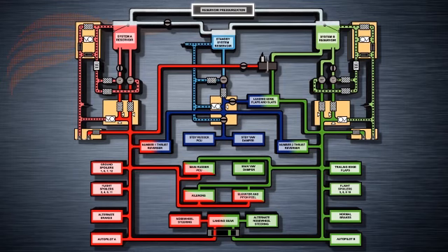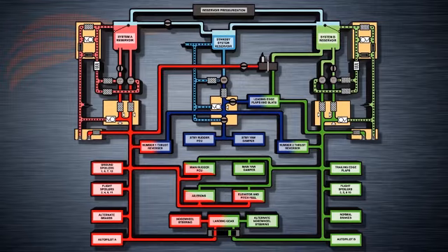If the bleed air switches on the forward overhead panel are selected off, then there will be no flow of air to the reservoirs to pressurize them. This is of course normal during a bleeds-off takeoff, and the hydraulic pumps can still function without bleed air pressure at low altitudes. Reservoir pressurization is there primarily for high-altitude flight, where the atmospheric pressure is not sufficient to prevent foaming and cavitation in the pumps.